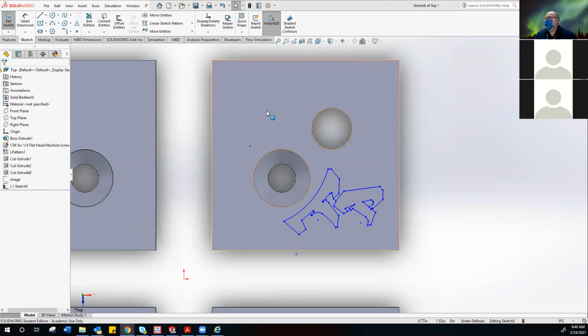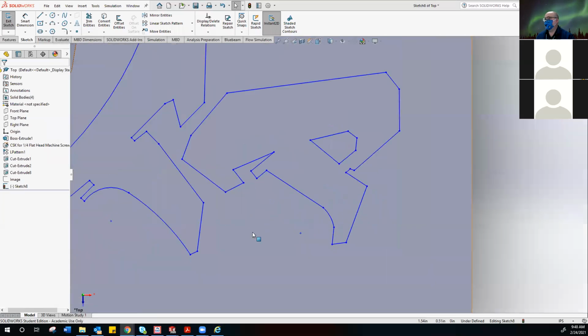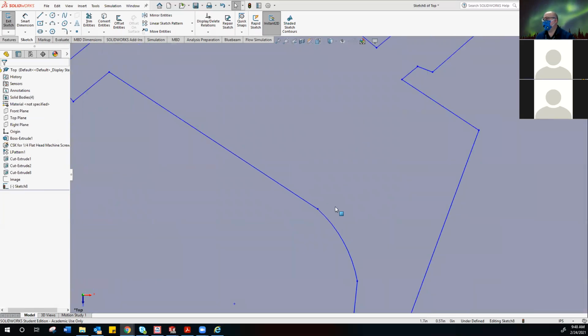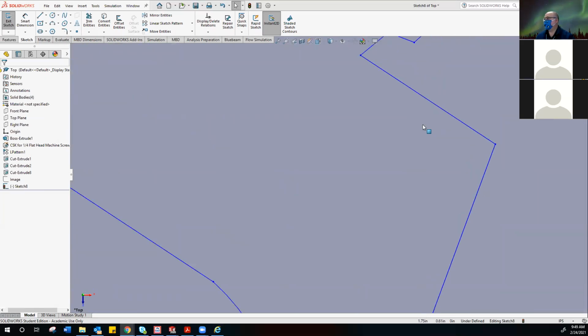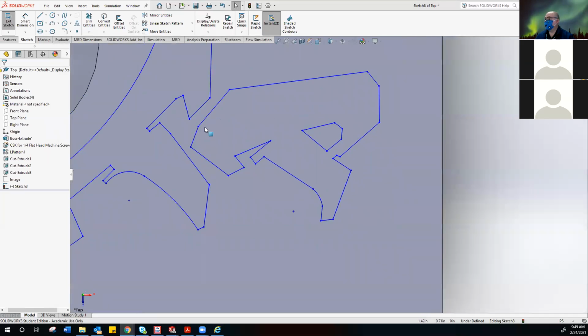Okay. Let's go back to testing. So I'm looking at my letters. They're not grayed out. That should be my first indication there's an error in my drawing, because if it doesn't gray out, that means I probably can't make it a 3D element. So when you get a lot of experience, 30 plus years, you can start saying, oh, I bet my mistake is a missing gap line that doesn't connect. And if you don't get them grayed out, you have to go and look at every connection point to find where the gap is.